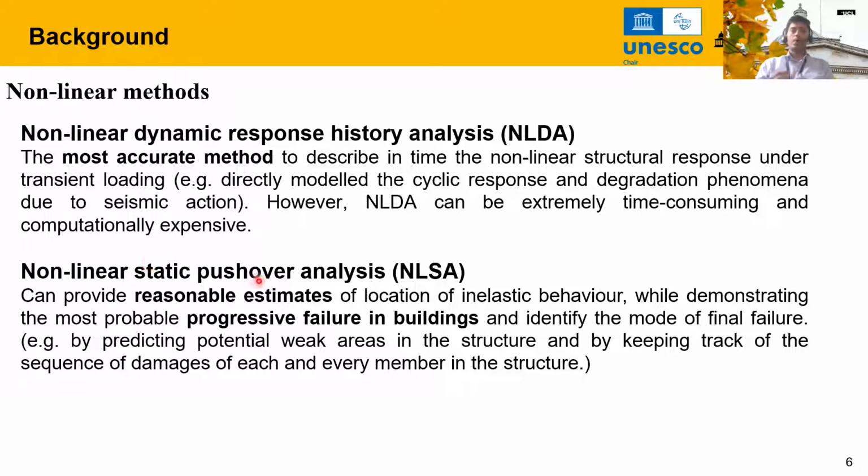analysis, where we use a computationally efficient approach, but we still consider the nonlinear behavior of the structure. Still, we use the static analysis approach so that we save time and effort. So the focus of this presentation will be on the nonlinear static procedure, which is midway between the linear elastic procedure and the nonlinear full time history analysis procedure.